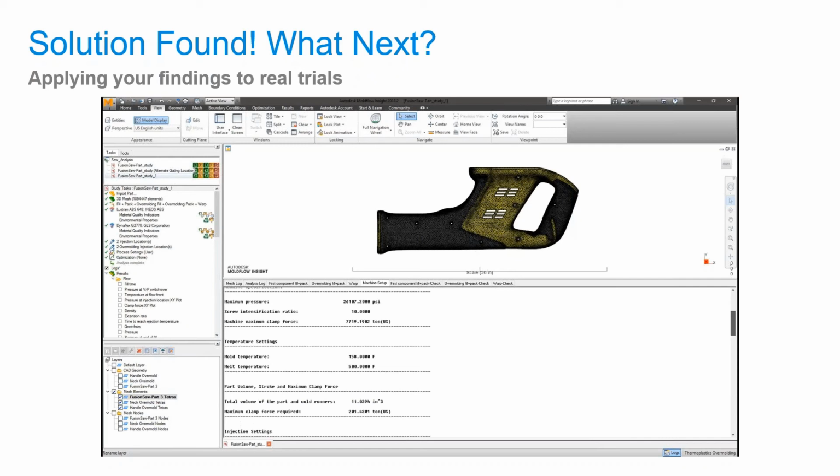If there are tooling changes needed, the best case scenario would be to work with your tool designer or tooling engineer to see how to efficiently and cheaply make those adjustments to the steel. You may need to actually work with them on the costs associated to making those changes and make sure they're justified before investing into that. Because sometimes a new mold could potentially be cheaper. I know molds are expensive, however, some changes could be expensive as well.